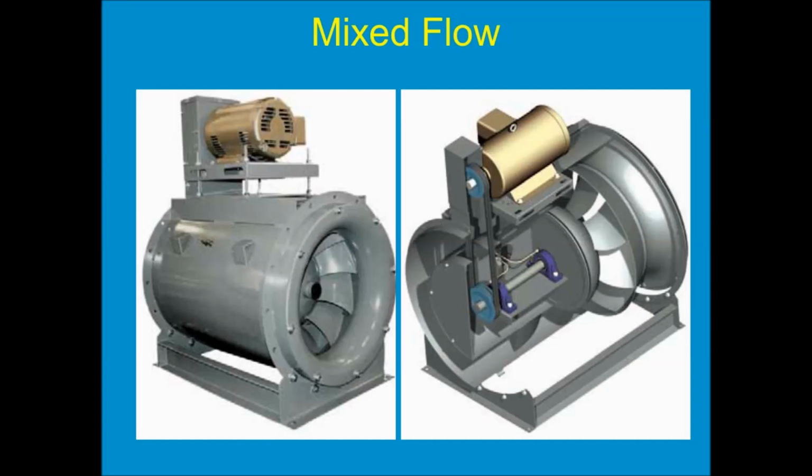So almost in every case, at least every case that I've looked at, whenever we're looking at moving a certain volume of air against a certain amount of pressure in an inline application, when we compare a centrifugal tubular fan to a mixed flow fan, the mixed flow fan can do the performance with a lower RPM, less horsepower, and less noise. So in those inline applications, it's just a better choice. It's a very, very efficient way to move the air.